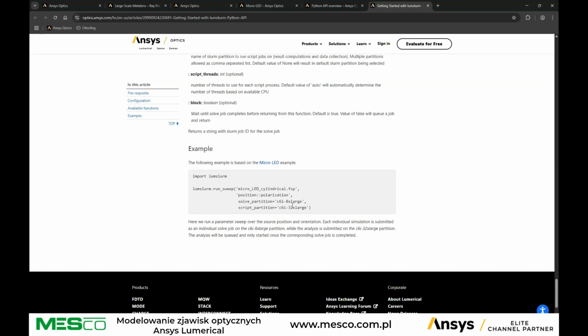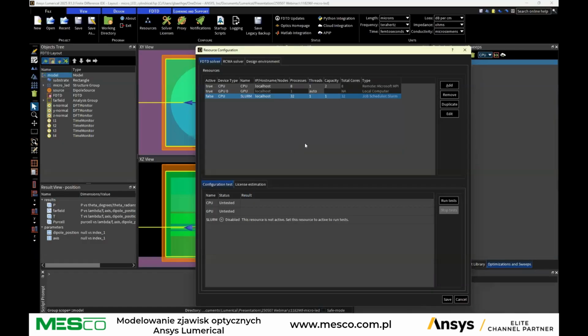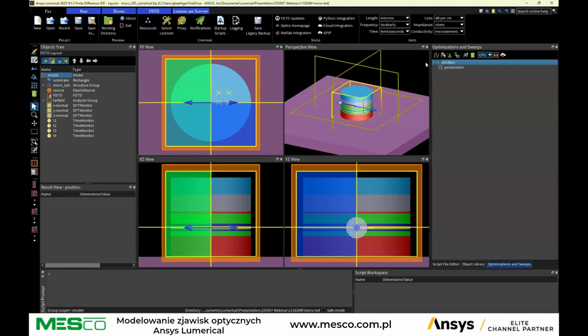And so why there is 67 jobs is because you have 33 jobs to run the simulations, the 33 simulations. You have 33 jobs for the processing, the far field projections. And then we have a last job that is to load all the simulations back into the main file. And when that is done, you have all your simulation files, all your results stored.